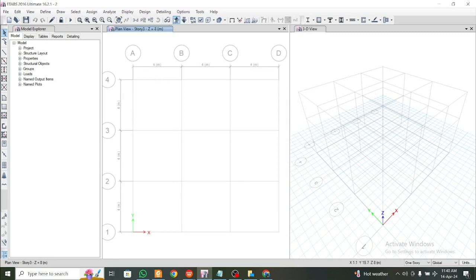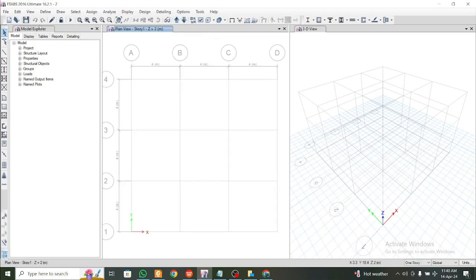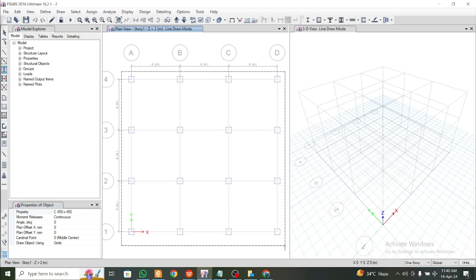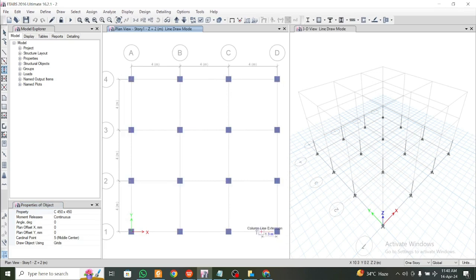Now let's just complete the modeling part real quick here. So let's go to the bottommost part. In the base level you cannot add the column, we can add the column from the plinth level itself. So we'll use this option here, quick draw columns, and we'll just choose the column shape, and we'll just give a column in every intersection here, and same for the beams as well.